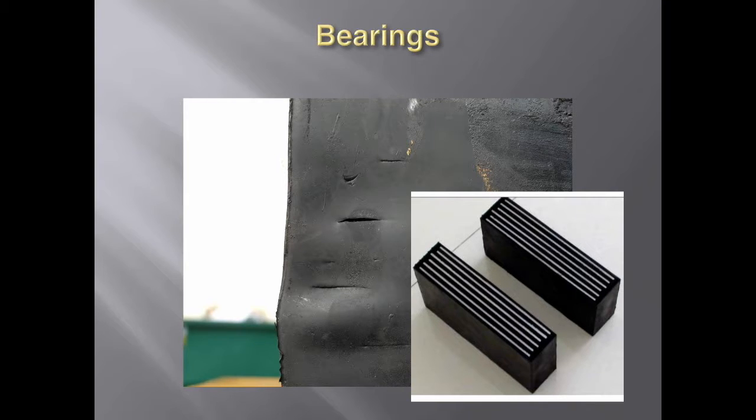I think there is like a 60-day lead time, so once you find this on your project, you've got 60 days before you're going to be able to get the girders or the bearings ordered and into the project. So when they do arrive on the project site, you need to make sure that they're handled correctly and not just tossed around. Usually we like to see them covered up and left on their pallets until they get placed.